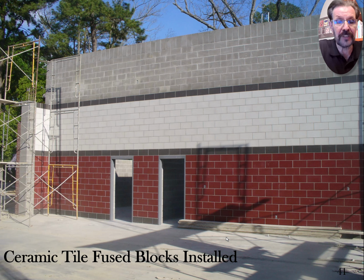Those steel frames are typically tied in as they build the wall. They are tying that into that frame, and so it's all about setting up that frame so it's perfectly level and plumb and everything, and kept checking it to make sure it doesn't move. But if you do it right and hold it in place, then it's fine.